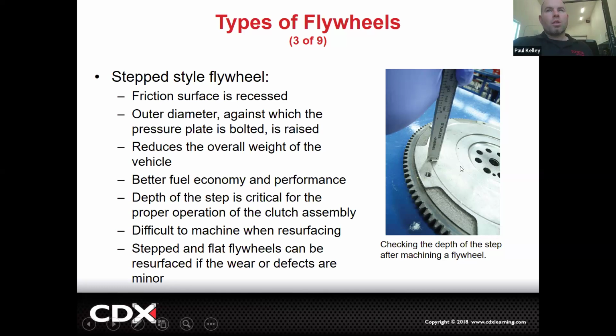Generally speaking, clutch release systems don't make them slip. Makes sense? Because if you bolt the clutch up, it's engaged. The purpose of the release system is to release the clutch. So how the heck is the release system going to make it slip? You'd say it can't, right? There's one exception. I'm going to come back to that. So if they mismachine the flywheel the other way, it may slip.